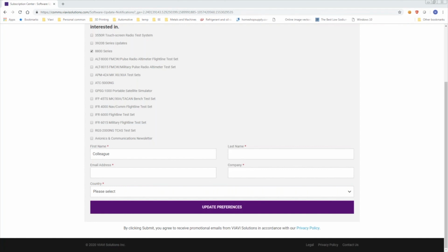Robert, when you put the cable loss in on the 8800, it does not need you to go in as a negative value. You can put it in as a negative value if you want to, but the 8800 is smart enough to figure out that the loss is going to be a negative, and so it will automatically assign the correct sign to it.